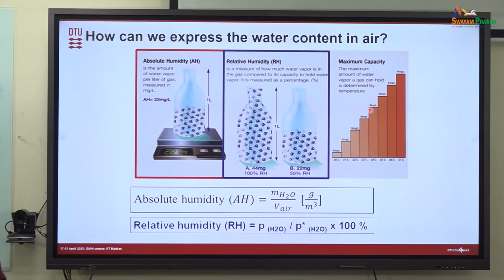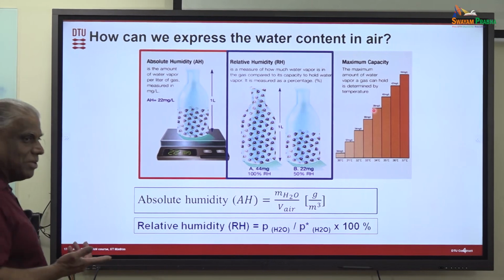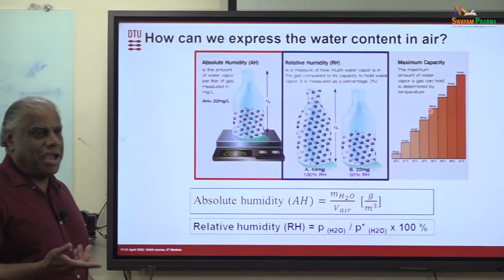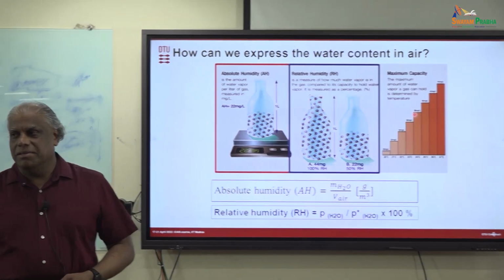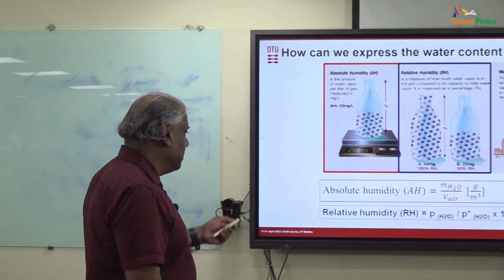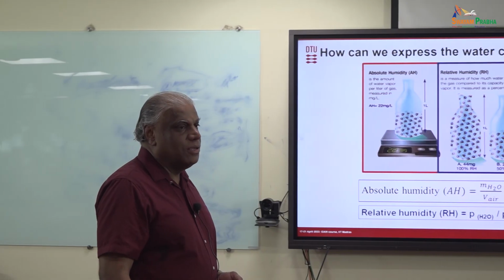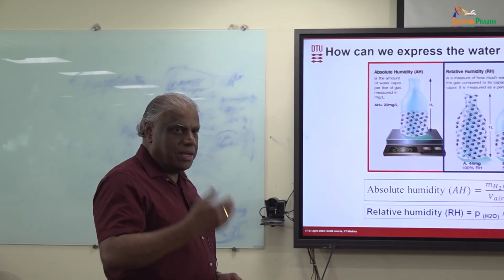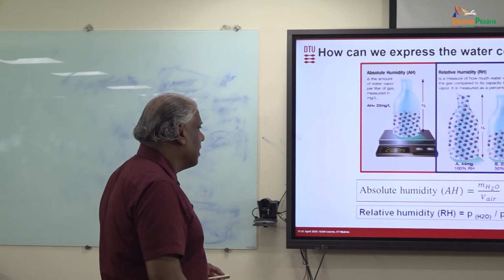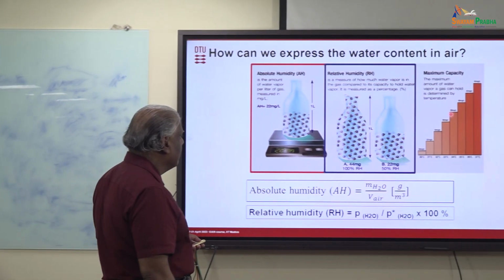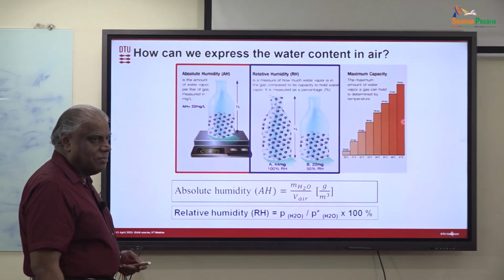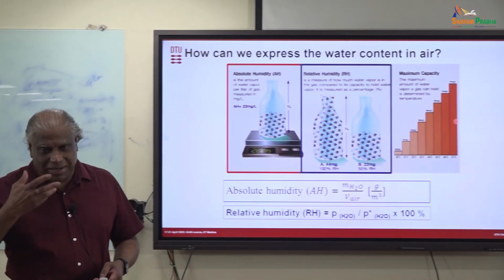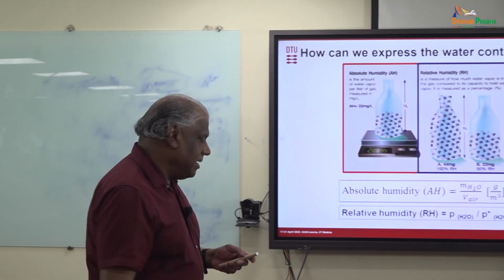So relative humidity will not tell you the absolute humidity level. Absolute humidity is not an easy way to express the humidity level like 50% relative humidity. That means that whenever you are doing modeling or something like that and you need to take into account the actual moisture content in the air, then you need to go for the absolute humidity rather than the relative humidity. But relative humidity is much easier for us to understand, and that way it's much better.